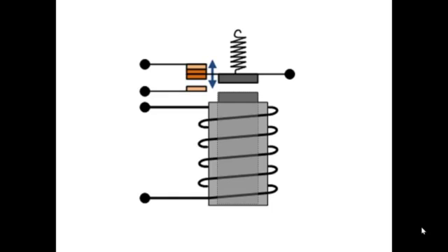The original control panels use relays for the logic, and the most common programming language today is relay ladder logic, and it evolved from the electrical prints and uses of the same symbols. As a matter of fact, if you look at an old electrical diagram for a relay control circuit, if you're a PLC programmer, you might at first glance think that it's an actual relay ladder logic program.